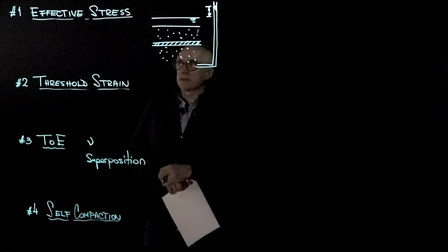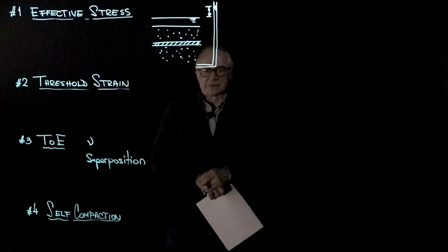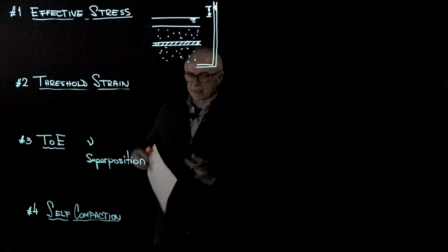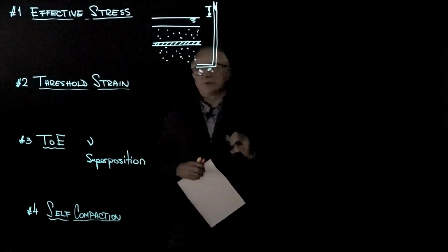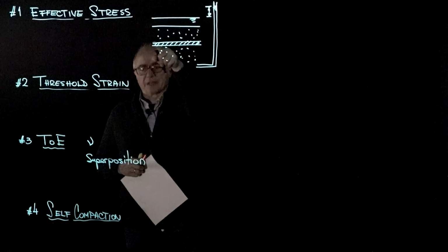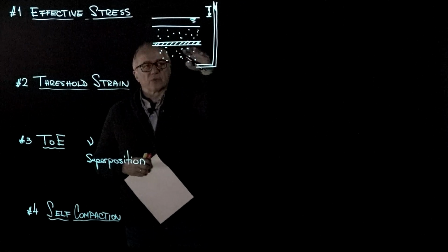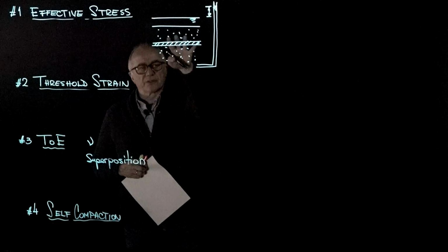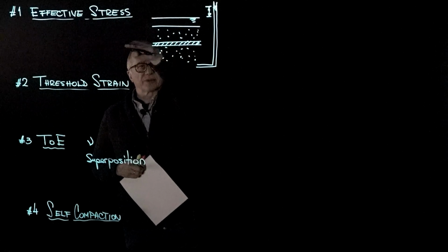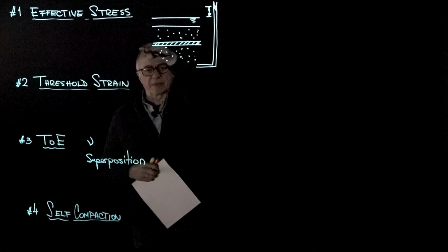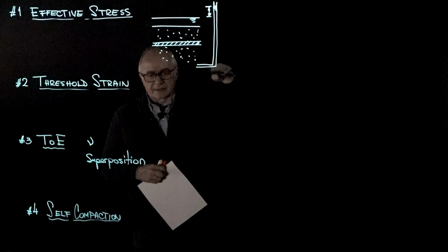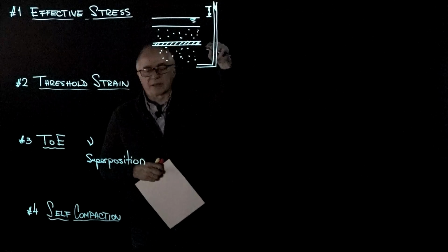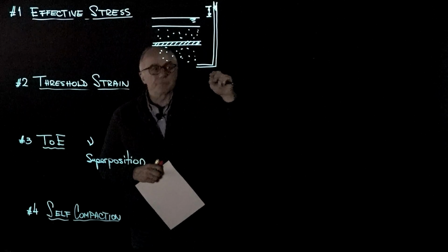The first question addresses effective stress. Please go back in each of the cases to previous recorded videos. But this one is the case where there is an aquitard. That means that water cannot migrate through. This is like, in the extreme case, imagine that we have a plastic membrane, but in reality it's the sedimentary layers that have placed there probably a thin layer of clay.